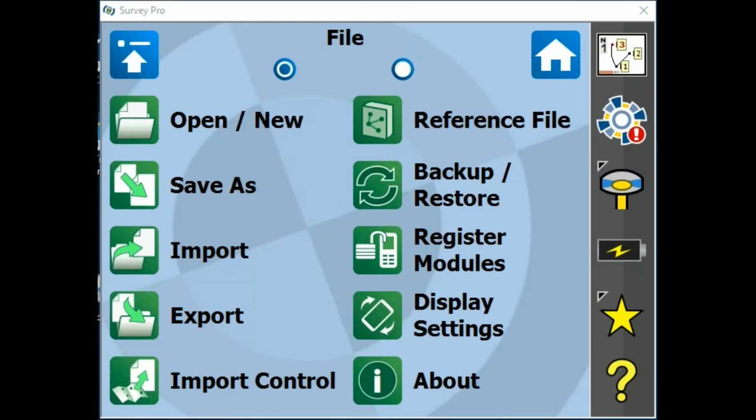So I'm going to go over here and I'm going to pick a text file and I'm going to choose a file for import. And I, of course, have the wrong folder. I had it all queued up. Stand by. There we go. I'm going to import some ground coordinates as if they had come from a total station survey from some time in the past. Meters, plane, we'll go ahead and finish. Quick look at the map shows us that we have a number of coordinates surrounding our...